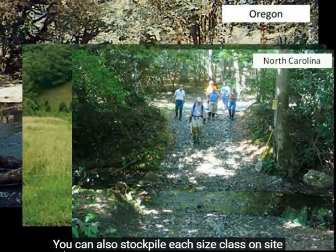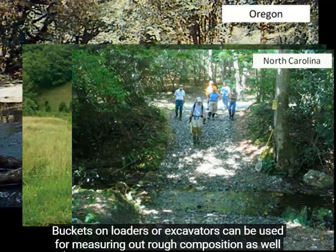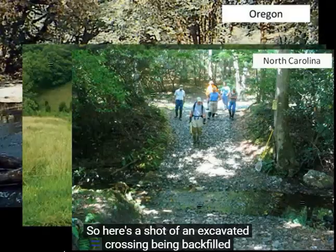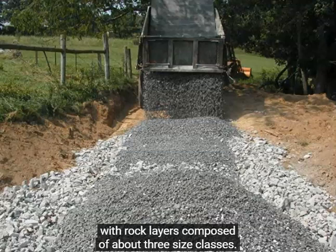You can also stockpile each size class on site and create the backfill mix using construction equipment at the site. Buckets on loaders or excavators can be used for measuring out rough composition, as well as on-site mixing before placement into the stream crossing. So here's a shot of an excavated crossing being backfilled with rock layers composed of about 3 size classes.